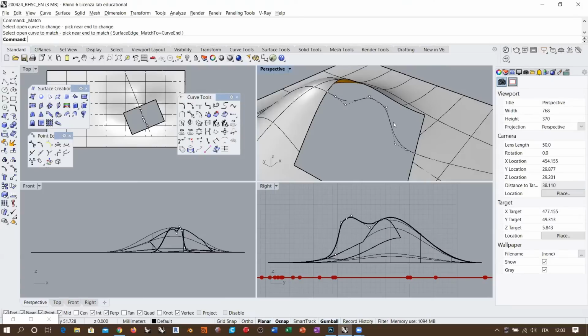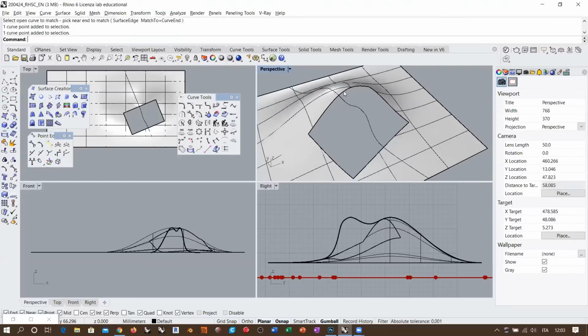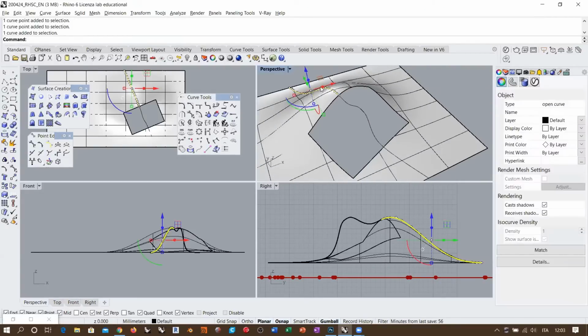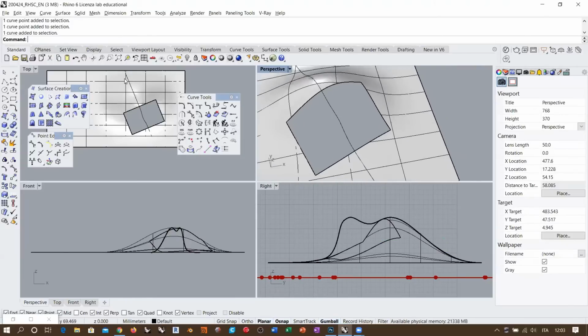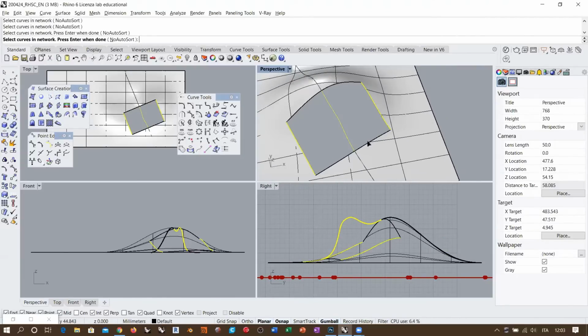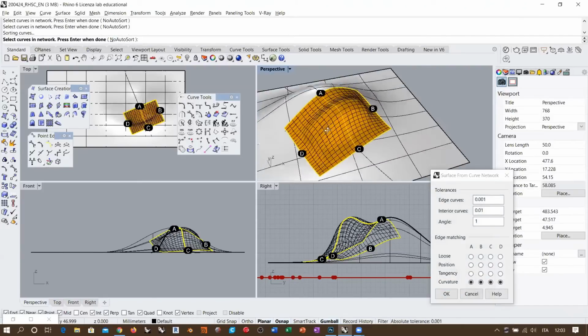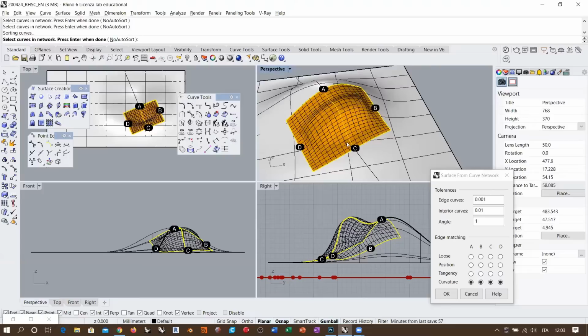So we didn't change the topology. We simply changed the position of these control points and this one, so that our cross section is actually curvature continuous along this edge with the correspondent part of the surface that's relevant, which is this and this curve. Okay, so now my network surface is going to be even more precise, because the internal guide is telling basically the same thing as all the rest of the edges that are involved.